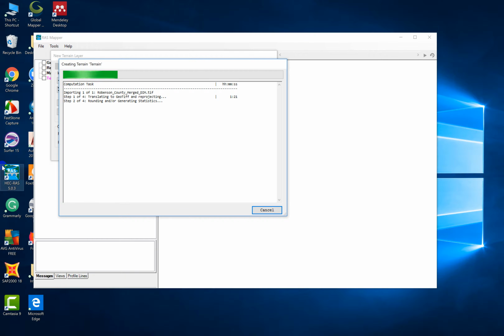And for the flow, you are going to define if it's steady or unsteady flow. A steady flow is for flow that is not changing with time. That means you have a constant flow, like a river in normal condition without any flooding. But in our case, we have floods, so the flow was normal, but it rises to a high level and then goes down. So it's unsteady flow. That is the difference between steady and unsteady flow.